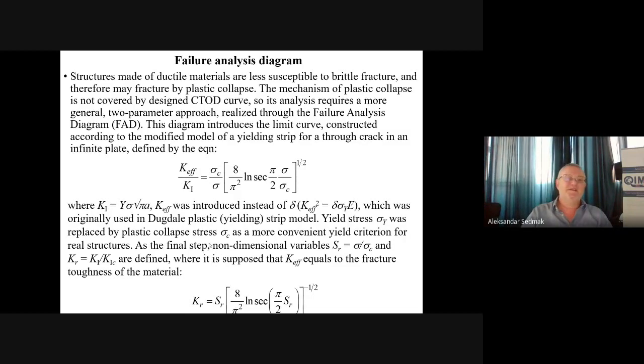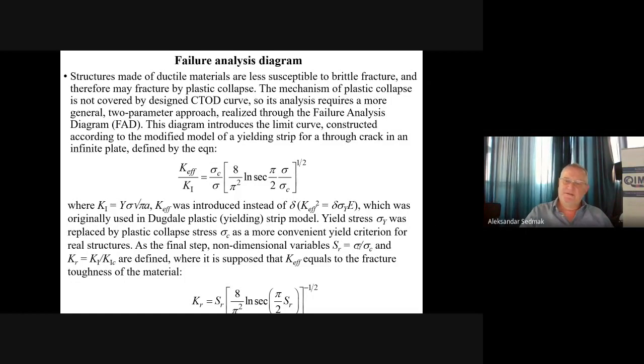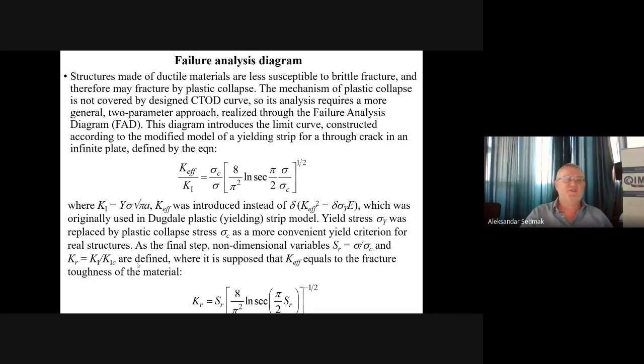Both the stress intensity factor and its critical value are taken as a ratio, you can see it here, and then net stress in the cross-section where the defect is discovered, and critical stress are also taken as a ratio, in both cases non-dimensional ratios, which are then correlated in the way presented here.